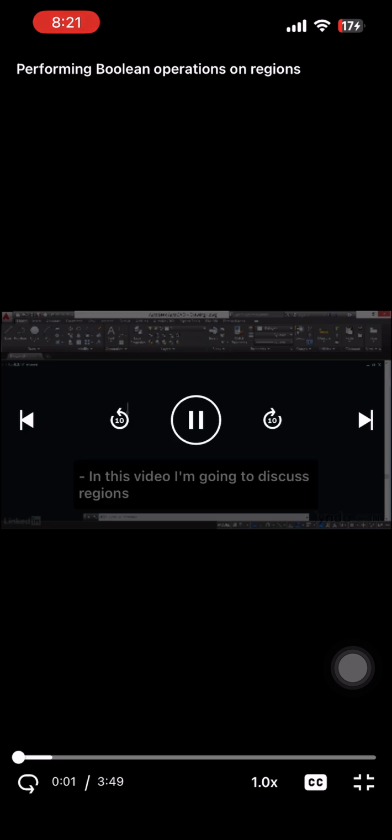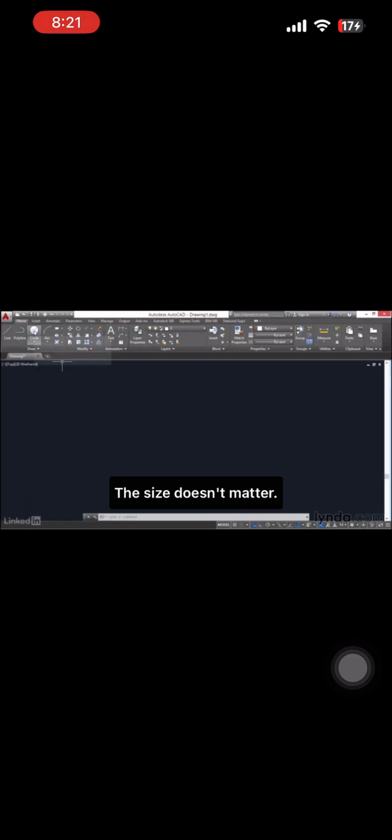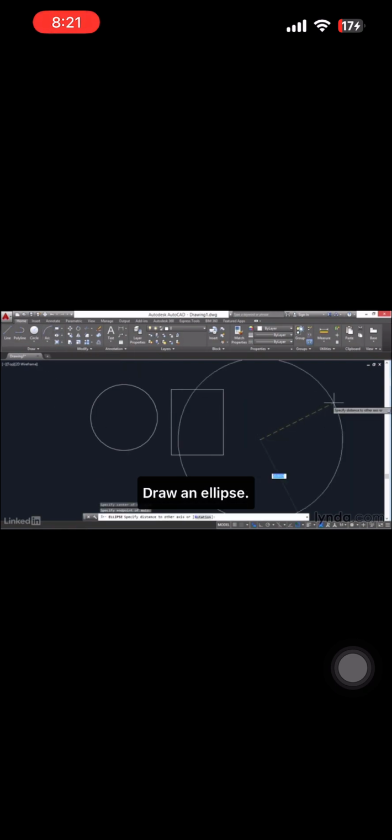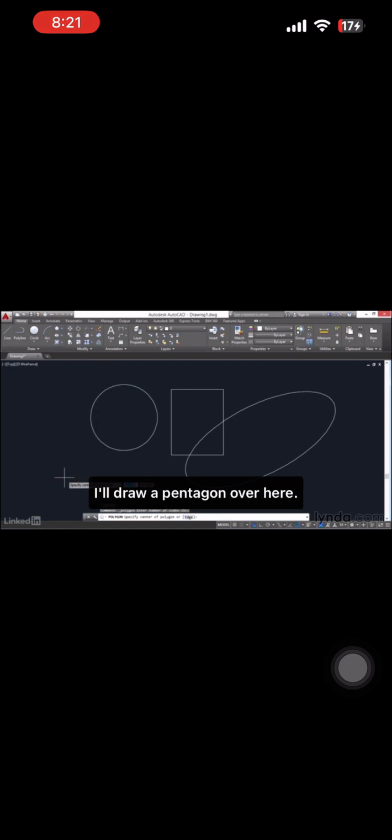In this video, I'm going to discuss regions and the Boolean operations you can use to manipulate them. Begin in a blank drawing and draw a circle. The size doesn't matter. Draw a rectangle next to it. Draw an ellipse and a polygon. I'll draw a pentagon over here.